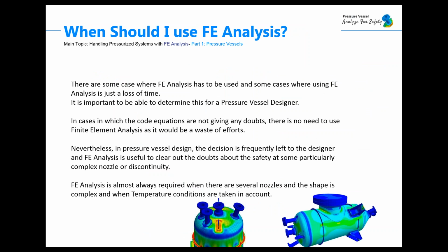So I'll have just a few words about FEA analysis in pressure vessels, because if you have ever used FEA analysis, you know that it's not always useful to actually perform it, and in some cases it's just a loss of time. So it's important to be able to determine this when you are working in pressure vessel design. And in cases in which the code equations are not giving any doubts, then you don't need to use finite element analysis, because it will be a waste of effort.